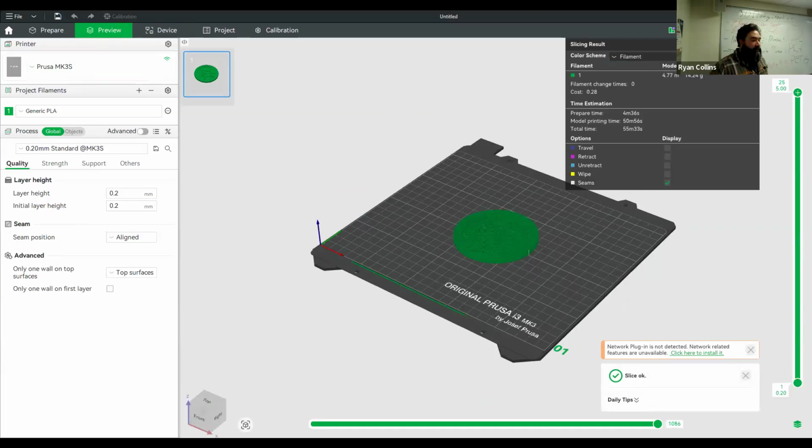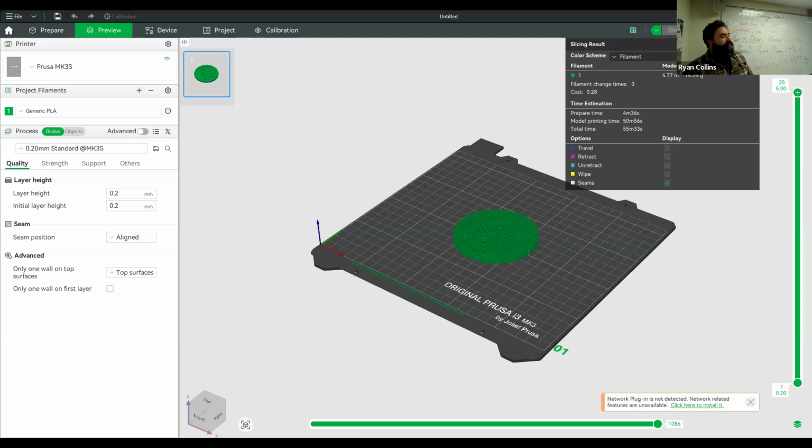So what it's going to do, now you could go to print if it's physically connected, but these don't work that way. So unfortunately, this is going to say export G code. Now, hopefully that's going to be the default going forward and it'll save that, but the other program does it differently. G code is the code that most CNC machinery uses. 3D printers, CNC metal lathes and mills or anything like that, same kind of technology. And Fusion can actually create pathways or G code directly to take to, say, a machine shop. Now you wouldn't do it because they'd want to generate their own. But technically, you can go right from Fusion to a CNC machine.